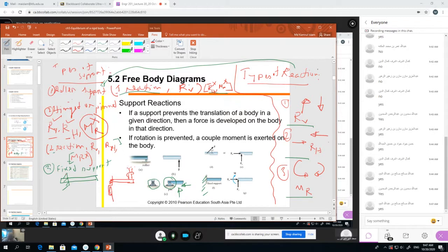Yes. So suppose this flower is 10 kg weight, so it is giving a vertical downward force. Now here at the wall where the joint is, it is giving the upward reaction, otherwise the cornice will break and fall down, right? So we have vertical reaction. Now if you try to pull or push, you cannot because it is fixed from inside. So we have horizontal reaction as well, right?